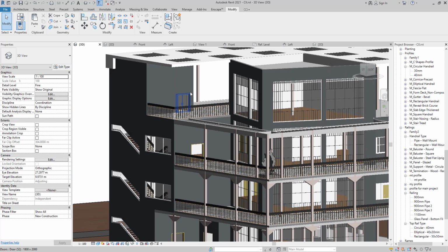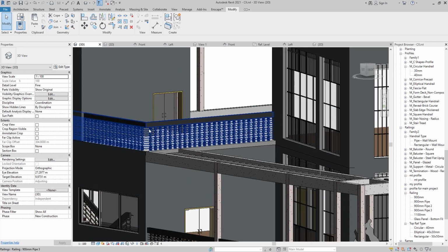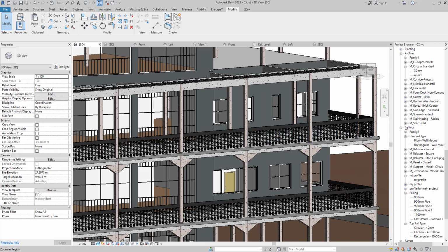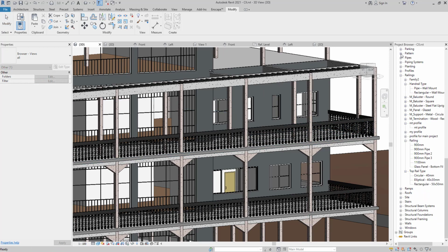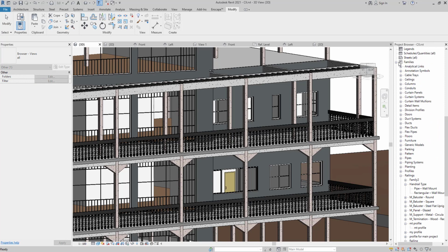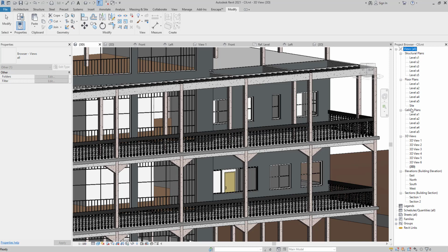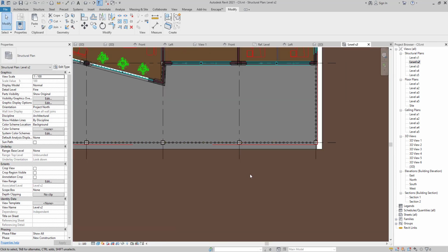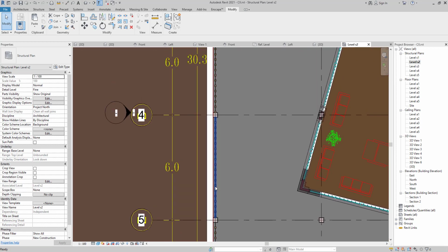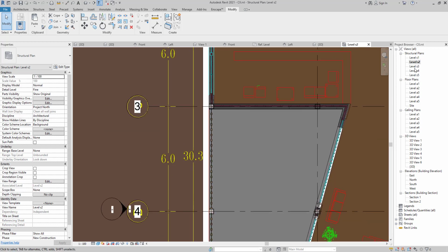So right now we know how to create railing, how to create baluster, and how to change the shape of our railing. The next step is to create or draft it in our project. So for doing that, I'm just going to close these elements here because the family, okay. For doing that, we need to go to our S4 because we created in our S level structure floor. So we need to go to, for example, S2, and I will check one of them which is wrong so I can fix it too. It was in S3.